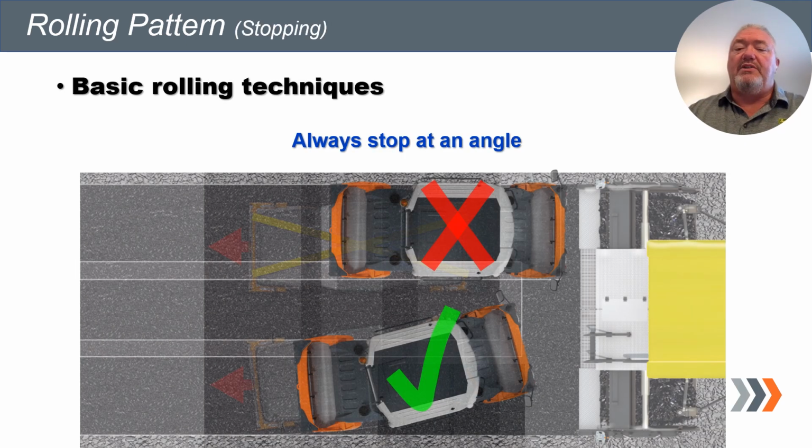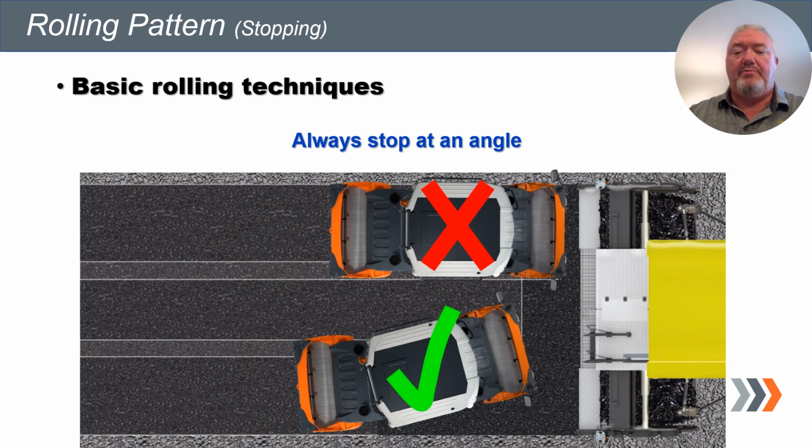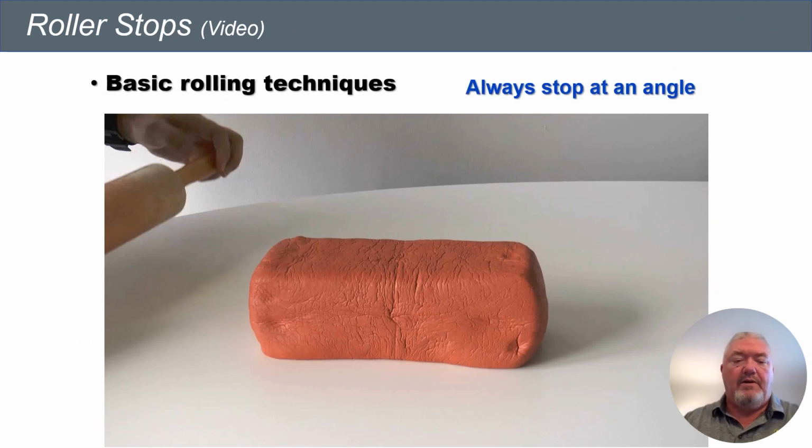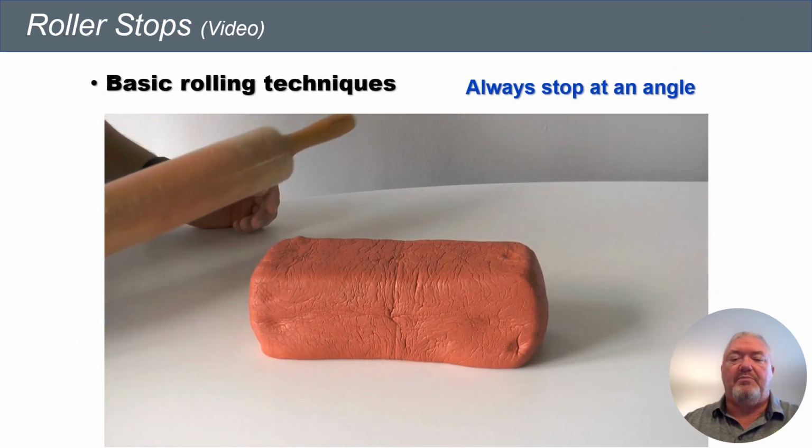We also want to make sure we never stop straight on behind the paver. We always want to make sure we stop on an angle. And the reason why is because it'll be a much easier chance to get the bump out.